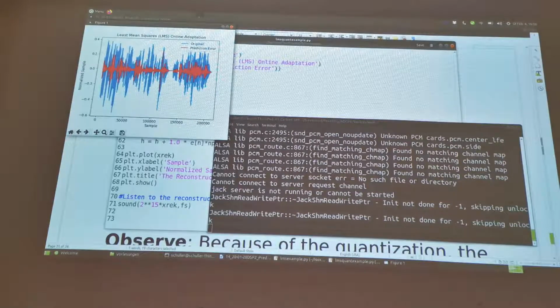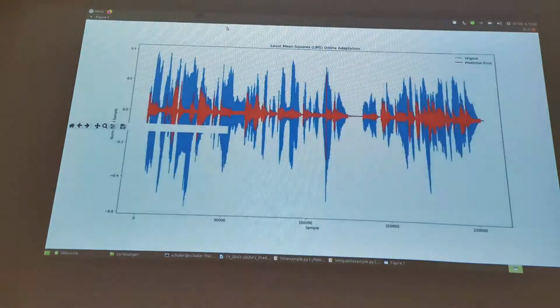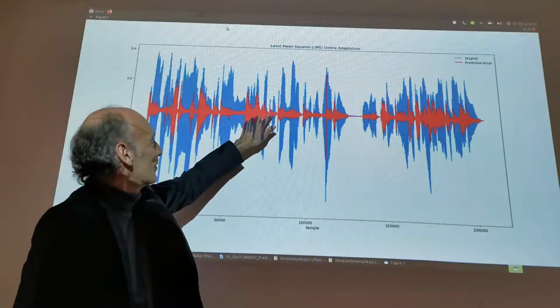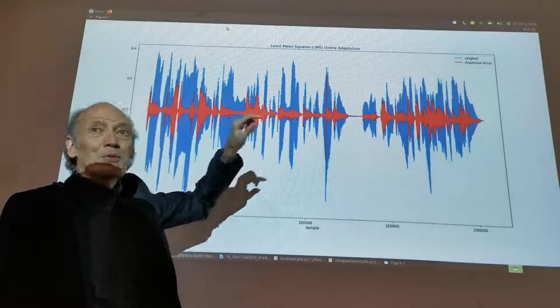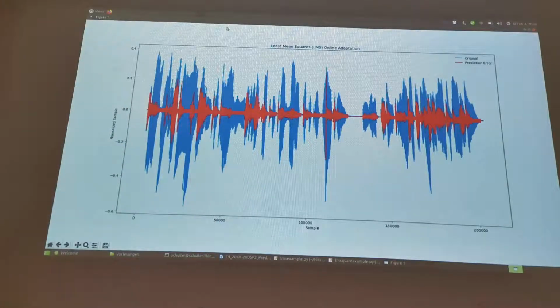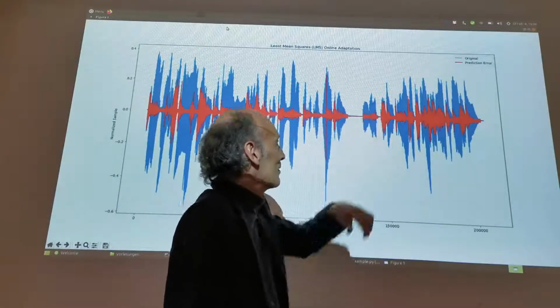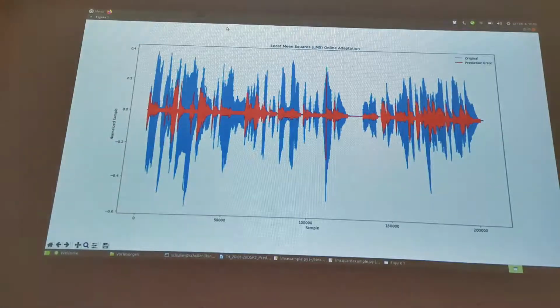Okay. Well, could you hear the quantization error? So there was some noisiness. And you can also see it here in this picture. So you have some constant noise, and you see the jumps which correspond to the quantization step size. Here you can really see this discrete behavior which comes from quantization. So you can see it, and you could also hear it slightly in the prediction error.